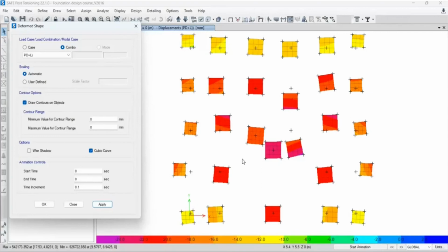Because we said that the pressure of settlement is directly proportional to the load over the area. So by increasing the area of your footing, you decrease the stress that is being applied to your soil spring, which will directly reduce the settlement. That is how you can solve the settlement check. So if it is exceeding 25 millimeter, you simply increase the area of your footing.